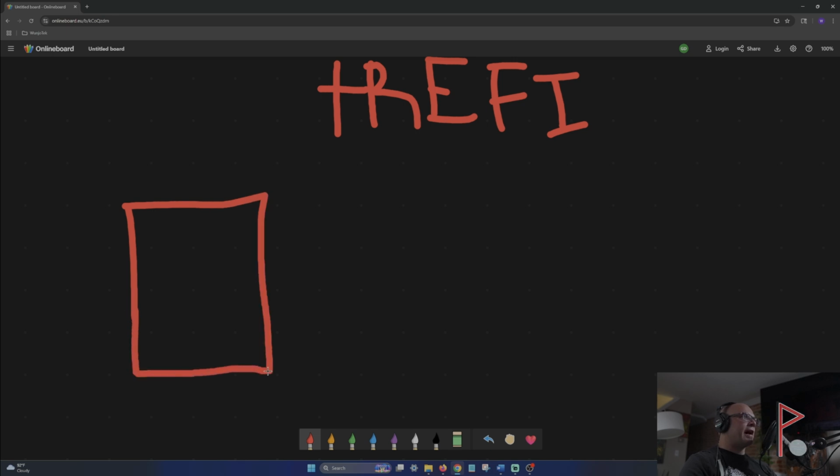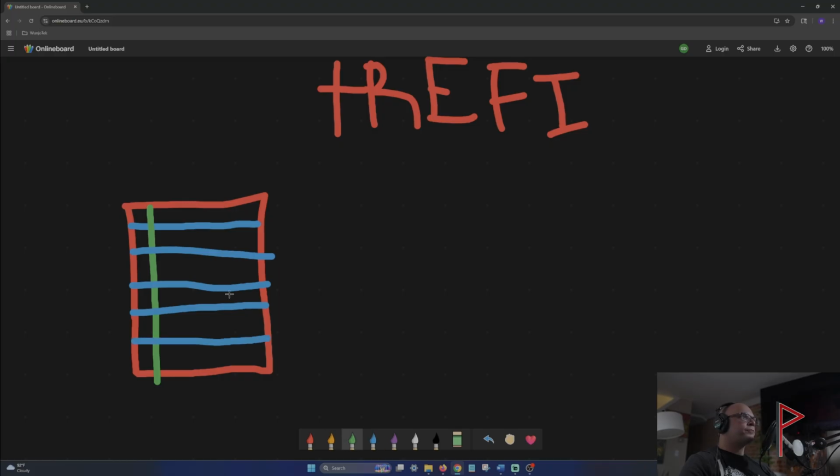And that die is, if it's an 8-bit cell, you've got rows, and you've got columns, right? And so these rows and columns, your rows are your word lines, and your columns are your bit lines.